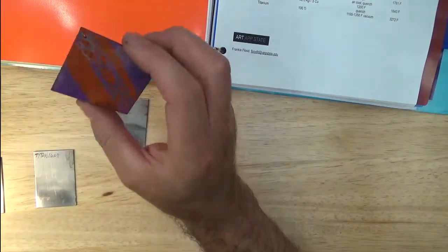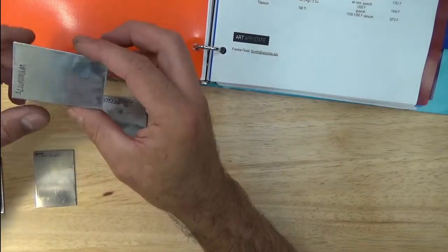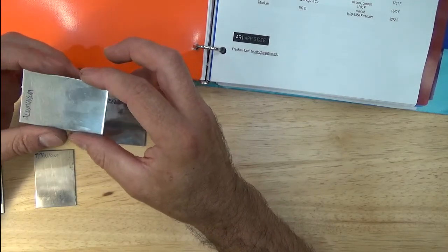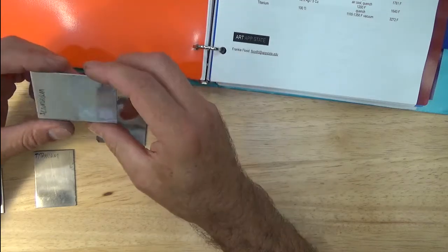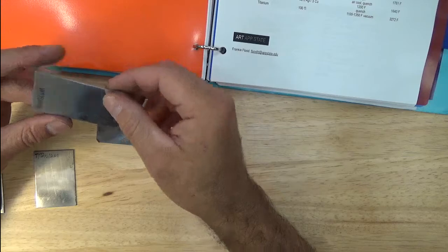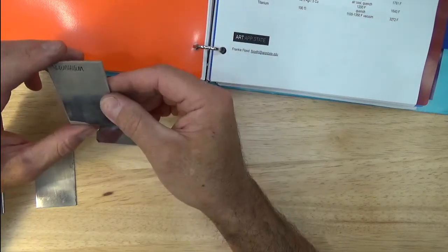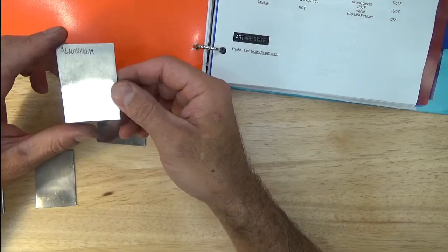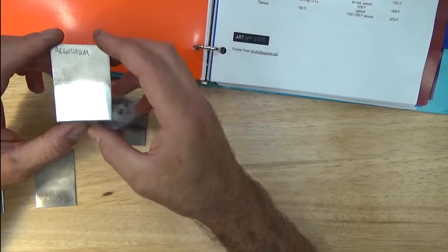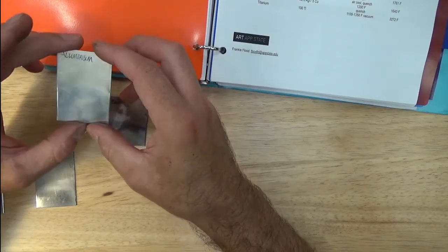Now, one last comment on this is that aluminum cannot be silver soldered or high temp soldered as we will with some of these other metals that we'll speak about today. So it must be cold connected. Now, it can be connected with heat processes, so it can be TIG welded, it can be MIG welded with a spool gun, but those are processes that we typically don't have access to here in this studio.